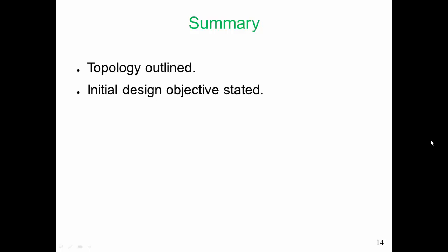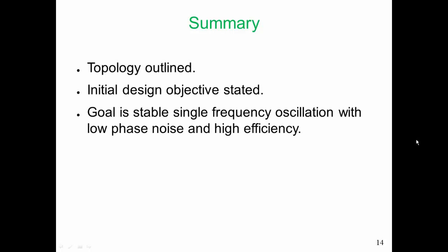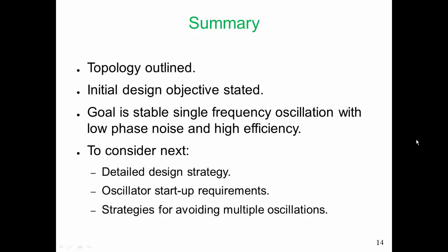Our initial design objective has been stated, and our goal is stable single frequency oscillation with low phase noise and high efficiency. So coming up, we're going to consider a more detailed design strategy, oscillator startup requirements, and strategies for avoiding multiple oscillations.